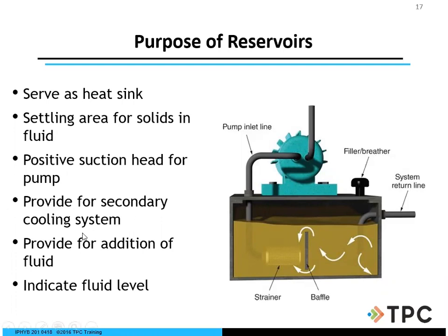Provide for secondary cooling system. Provide for addition of fluid. Indicate fluid level. The reservoirs are critically important. On this side over here, we have sight glass gauges. Make sure those are always clean. I've been into a lot of plants where the sight glass gauge is not clean at all. So how do you know what your fluid looks like or how much fluid you have in there? So keep your system nice and clean the reliability way.